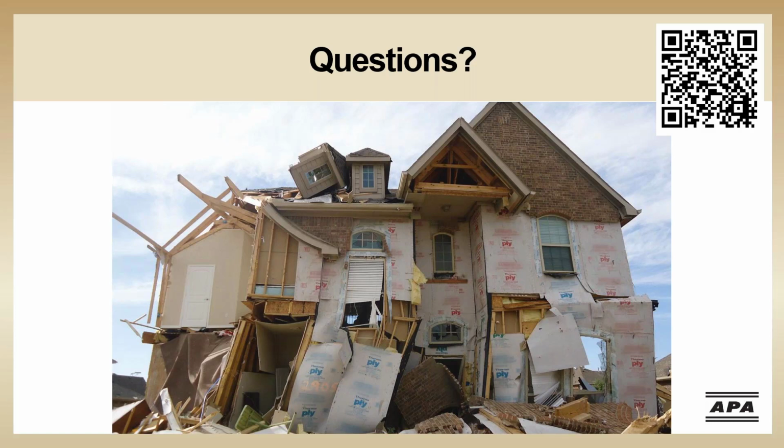Yes, sheathing is designed and can be exposed to moisture for a limited period of time, and it'll regain its strength once it dries out. So I would say as long as the fasteners that attach the roof sheathing to the framing are still intact, since they were subjected to a higher wind load, that does need to be verified. But if they're still intact, it does not have to be replaced. You should be able to just re-shingle once the sheathing dries out.